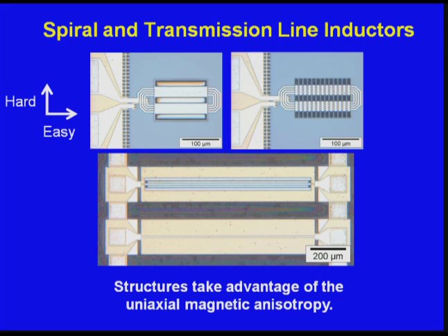So we set out to make some structures. Shown here is a spiral, another spiral with magnetic material that's actually patterned in stripes, which is to help reduce the eddy currents. And then the holy grail for voltage converters, and that is a stripe inductor, where we have a stripe here without magnetic material and one above it with magnetic material wrapped around it.